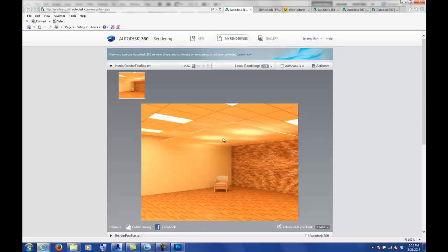But you know, you're going to have to manually make some kind of perforated cutout in order to make that render right. But if you want to do something real quick and you didn't want to go through all those curtain panels like we did in the second class, you could apply a cutout and kind of get a similar idea. The one thing that you're going to be limited to is your material can only be white or black. So if you want different materials and other things applied to it, you'd really want those curtain panels instead.